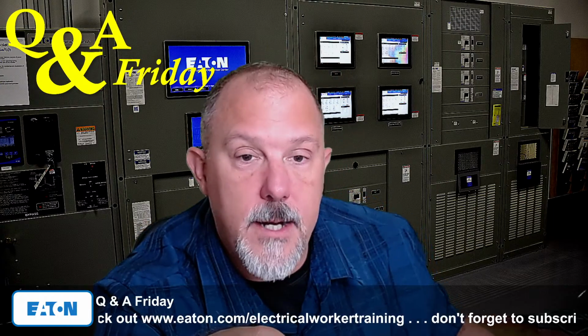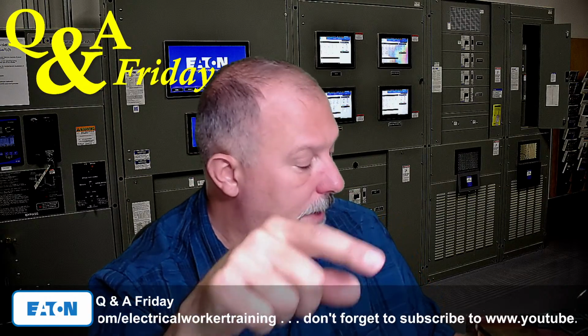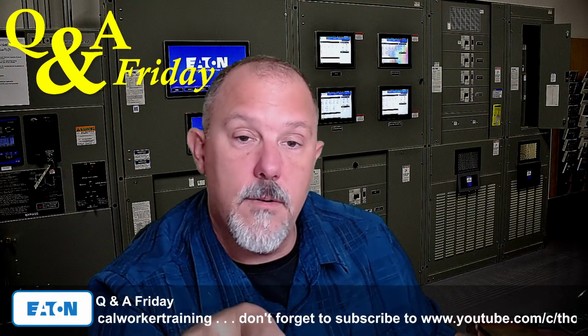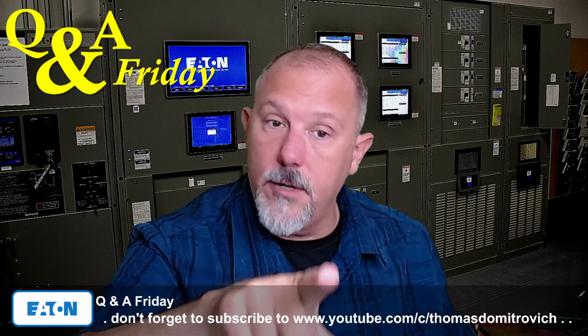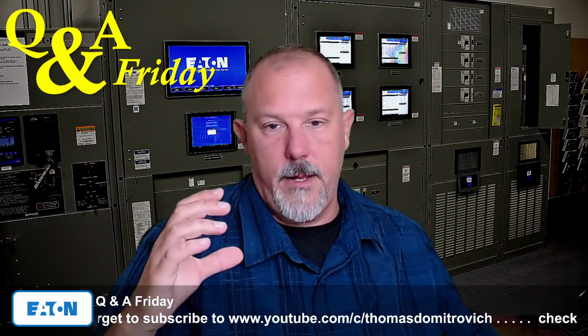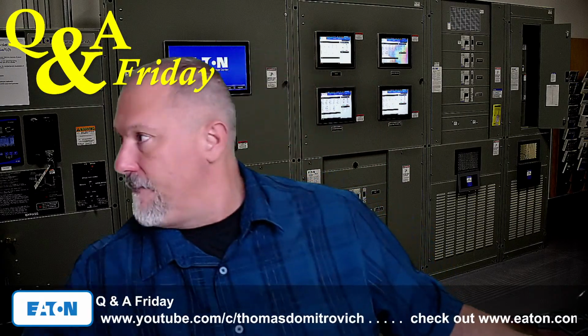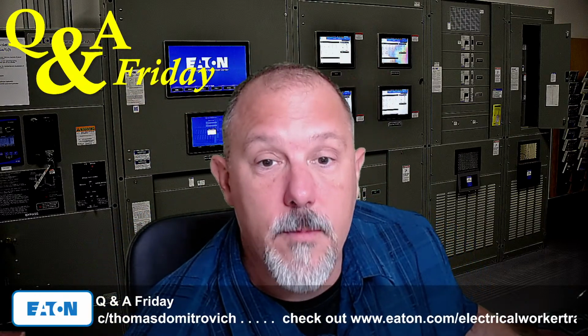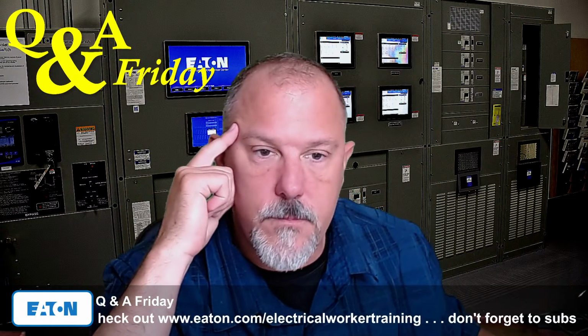So, shouldn't they be using the term long time pickup? And they do, JW. They say long time pickup setting. So I would agree with you, and it is in there in a parenthetical. So they're relating the rating with the long time pickup with the rating of the adjustable trip breaker.